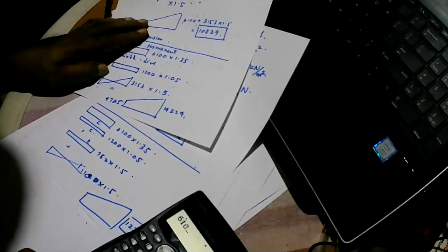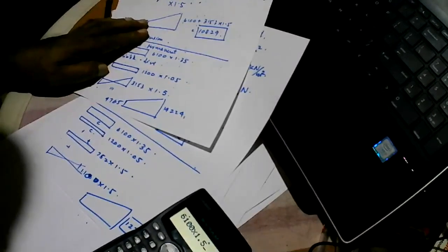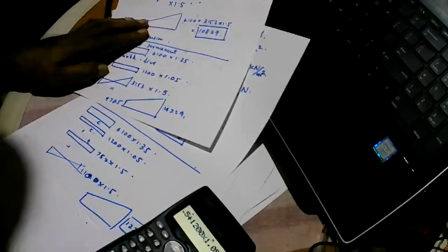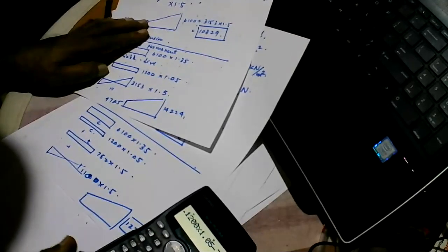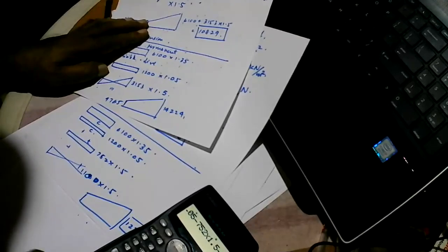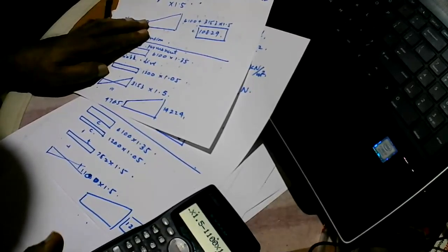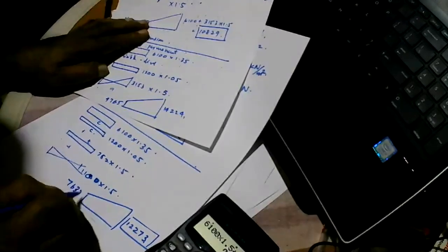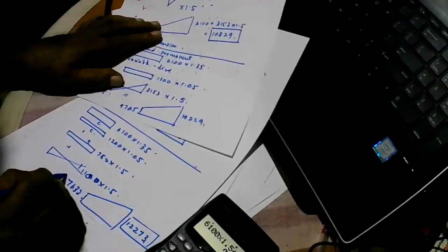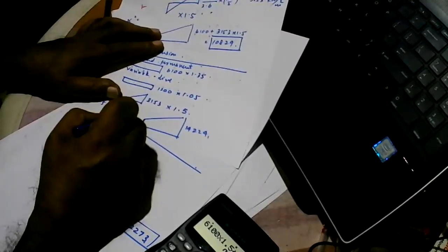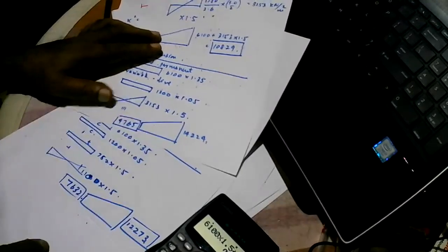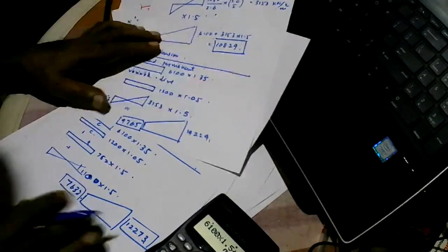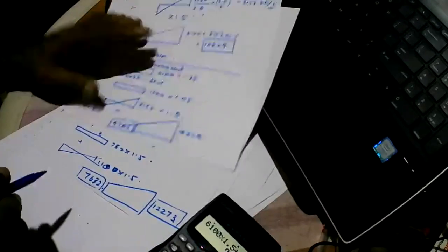Now we get 6,100 into 1.5 plus 1,200 into 1.05 minus 752 into 1.5 minus 1100 into 1.5. So we end up with 7632. So you can see it's better with tension as well. Earlier you get a lower compression, which means there's a chance for going into tension if the wind load is high, whereas here we get a higher value.